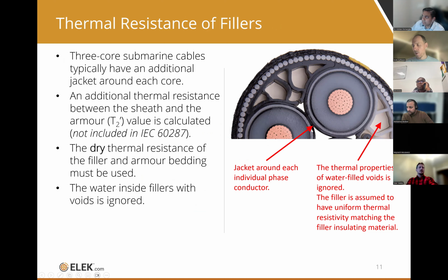That's the first arrow on the left. There's a thin insulating jacket around each core and around the sheath. And then you have these profiles, what are called profiles. That's those plastic frames that are holding the cores of the cable together in this trefoil triangular arrangement.